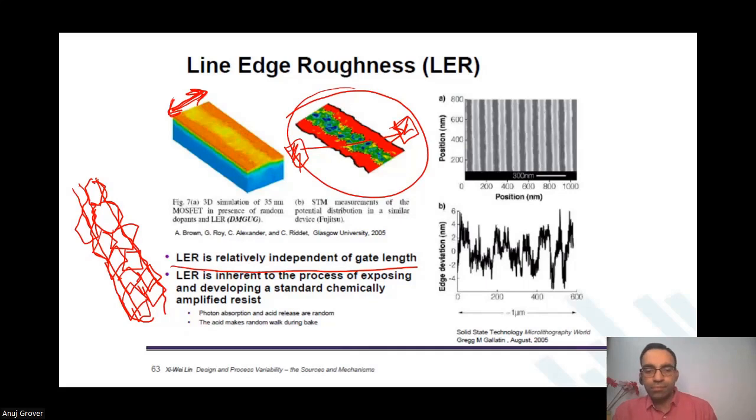Sir, the mask which you make, that will be made with the help of light, right? I think that's what he was mentioning before. Yeah, and that is what I'm clarifying. It is not about the mask at all. It is about the process of etching, the chemical removal of the extra polysilicon, so that only polysilicon wires remain. That is what I'm clarifying.